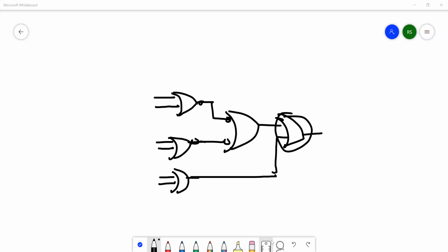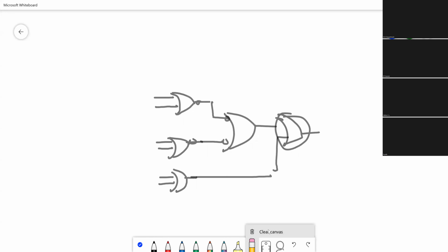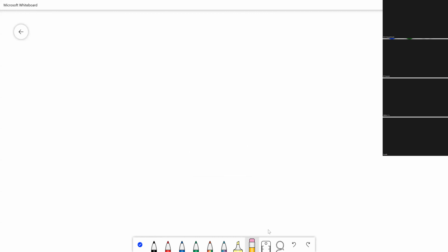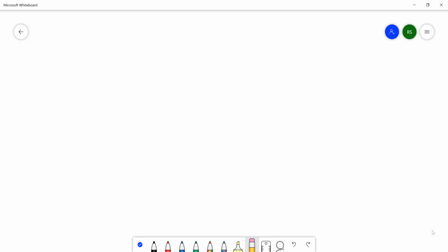So what is the meaning of this input ordering? First of all, we have to remember that in practical circuits, I've done all this in Cadence, we only give the inputs, right? V pulse, V use, and many times the inputs are basically coming at the same time, meaning that you give the V pulse period, something like 5 nanoseconds, 10 nanoseconds, and the inputs are rising at the same time.